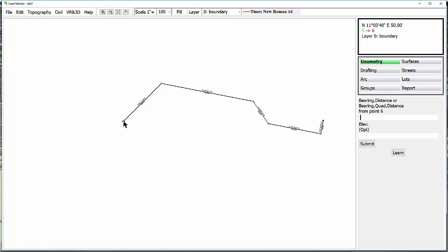Quadrant 8, let's say I want to go curve to the left, so I'll say negative 89 degrees, 45 minutes, quadrant 8, and a radius of 300 feet. It swung an arc, and you can see the information on the top of the screen of what it computed. Again, I'm looking at a foresight. If I want to continue along the tangent, I just say 0.6 and 150 feet, and that would be along the tangent.